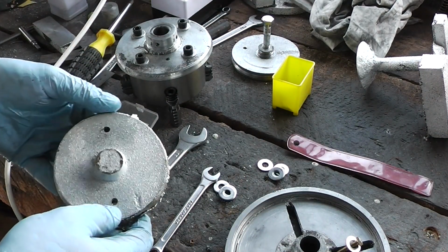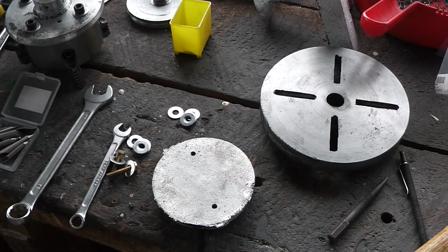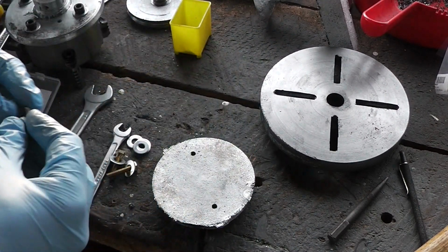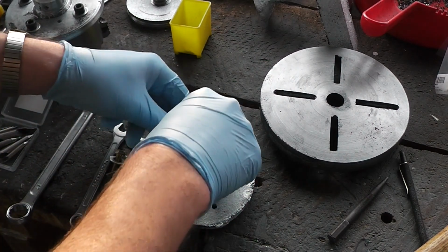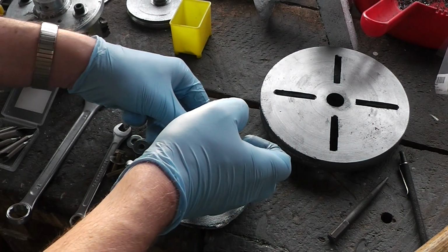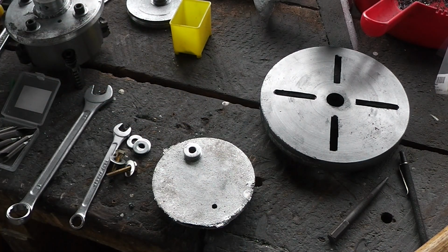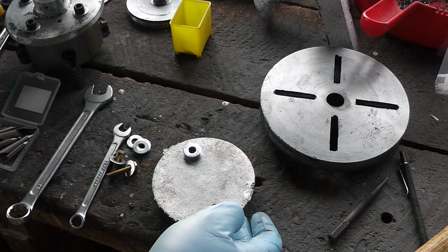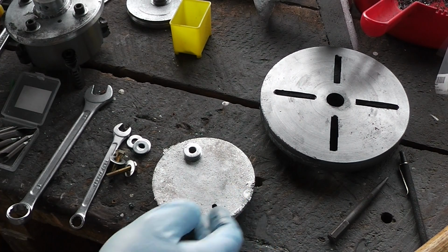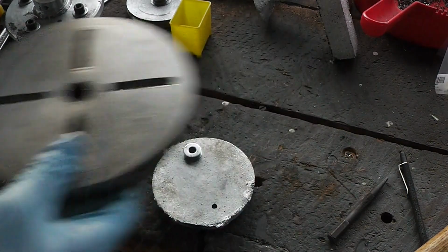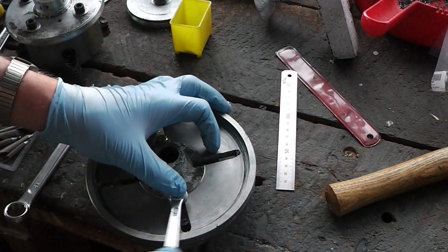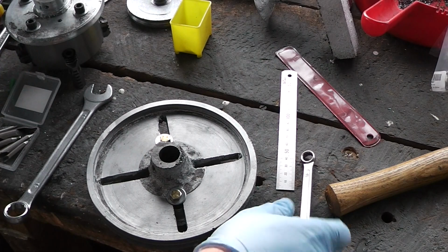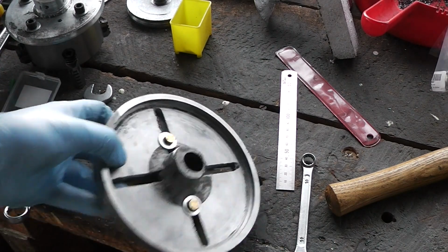I just have to turn up this one. I'm mounting these on the faceplate using a stack of 4 washers as spacers, which isn't ideal, but I don't have any better because I don't want to use one of my 1, 2, 3 blocks because I'll end up chewing into the block when I face down the edge of this rim. Otherwise I would use the 1, 2, 3 block. Going to get that a bit closer when I'm working on the lathe.